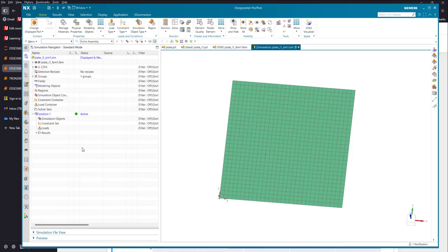Okay. So in this case, we only have constraints. Okay, so remember on this left side, so the x equals 0 line and the x equals 1 line, we have insulated boundaries. So we actually don't set anything there. And if there's no elements joining this edge, then there's no heat transfer. So we don't have to worry about that for the case of insulated.